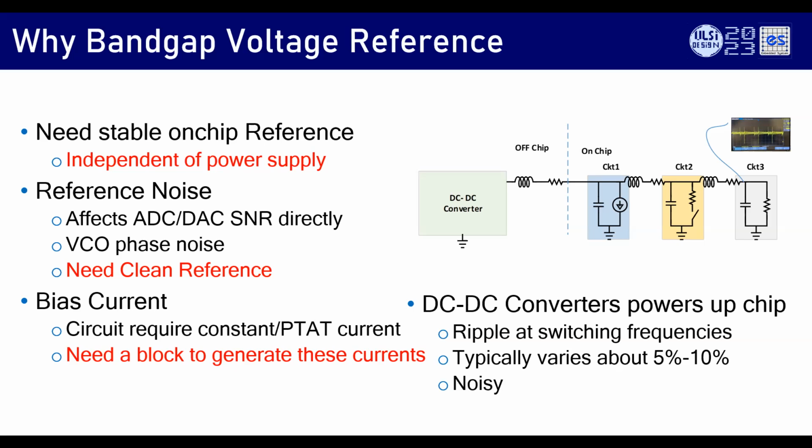The answer to that is that these reference voltages are given to, let's say, an ADC or a DAC to convert a dimensional quantity to a dimensionless quantity. It's analog to digital. Let's take an example. You have an analog voltage, you compare it with a reference, and you give a digital quantity. So whatever you give on the digital output depends on the reference. Now if you add some noise, or if the reference voltage is uncertain, whatever you're going to get on the digital side is going to be cranky. So this is not good, and this gives a lot of errors.